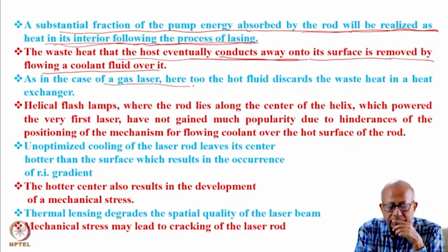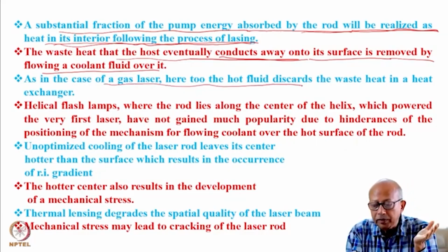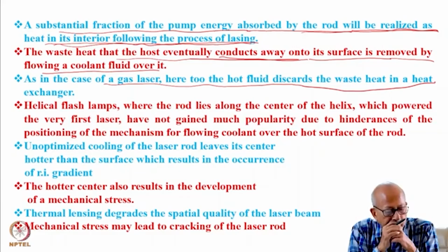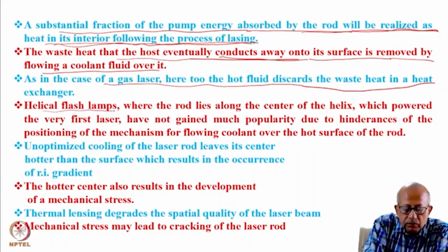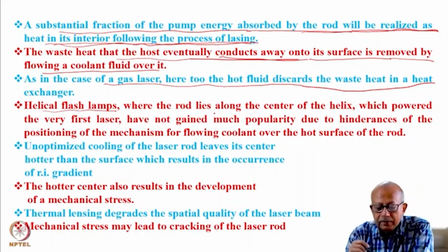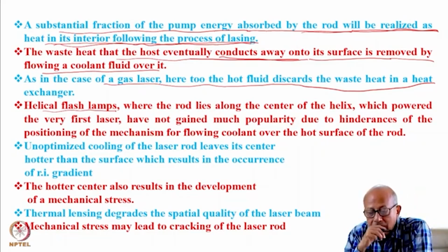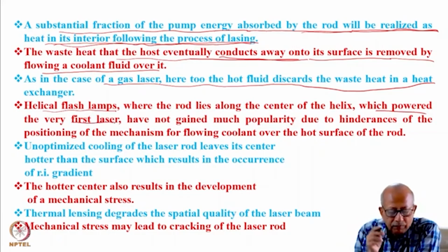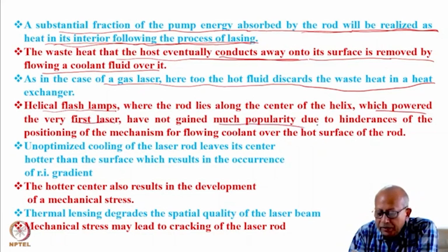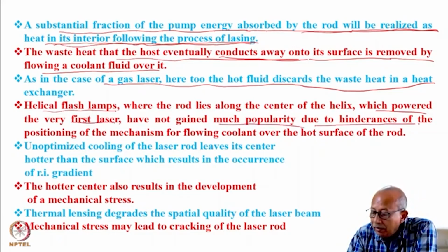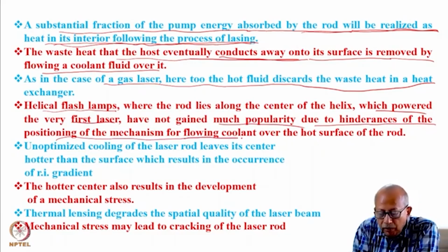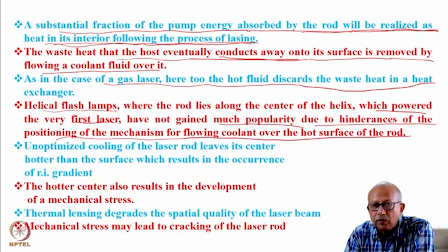As in the case of a gas laser, here too the hot fluid discards the waste heat in a heat exchanger. Helical flash lamps, where the rod lies along the center of the helix, which, as you know, powered the very first laser, have not gained much popularity due to the hindrances in positioning the mechanism for flowing coolant over the hot surface of the rod.